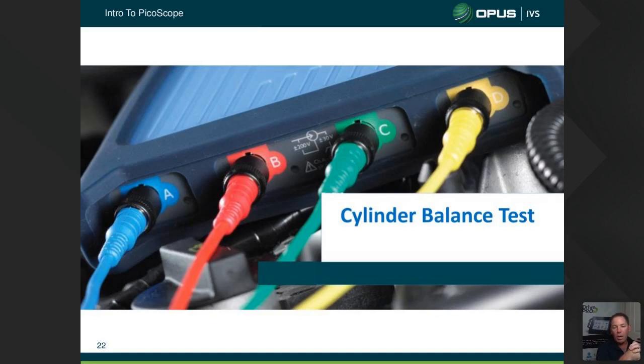It might be okay on a solenoid type diesel injector, but if you're doing it on a piezo injector, you're asking for trouble. The thing with piezo injectors, we use current flow from the injector driver or the ECM in one direction to open the piezo. So we expand the stack to open the injector. But then inside the ECM, we reverse the current flow and power up the injector, and that basically closes the piezo stack, which allows the injector to close.